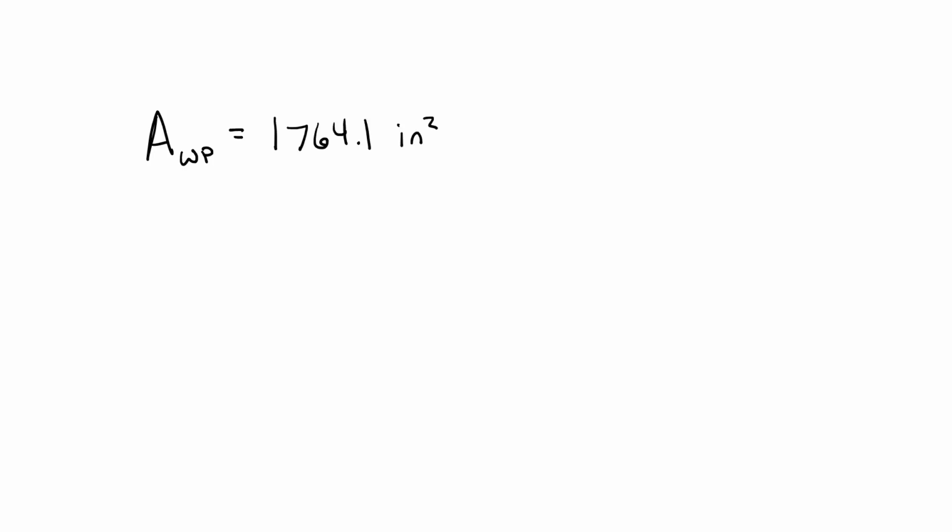Finally, I calculate my pounds per inch immersion. This roughly tells me how much additional weight is needed to gain an additional inch of draft. So my equation for pounds per inch immersion is my area of my waterplane divided by the factor of 27.7 cubic inches per pound.